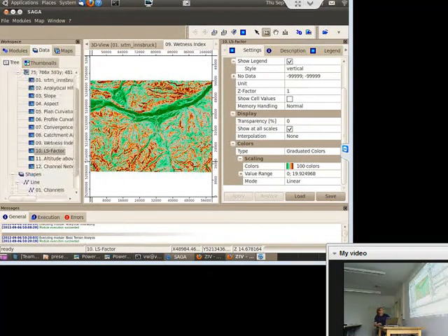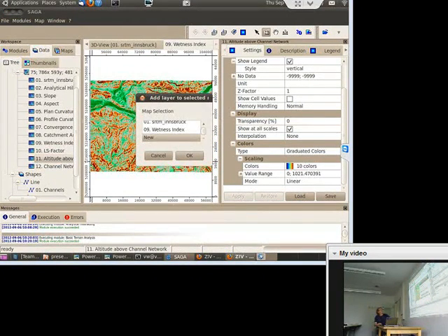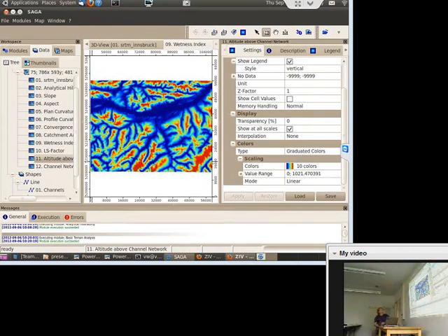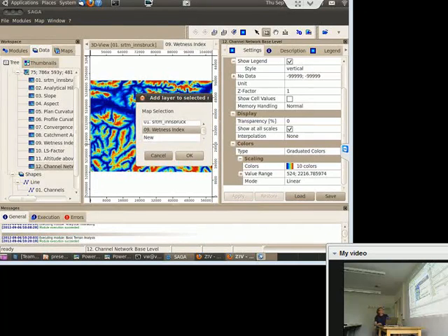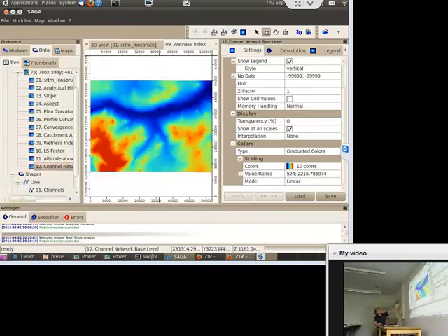And then we have two grids, which are quite interesting. One is showing the altitude of a cell above the channel network. That is more or less how much potential energy is available to the erosion base. And the complementary grid is, how is it called exactly? I have to scroll. Channel network base level, which is something like an estimation of groundwater height, because it's interpolated from channel network to channel network, from stream to stream, trying to follow something like a groundwater table. It's not very useful here with this steep terrain. But in case you have not that steep terrain, it's providing quite interesting results.